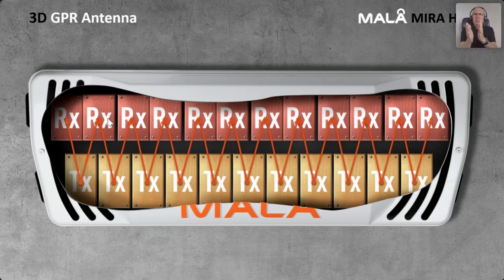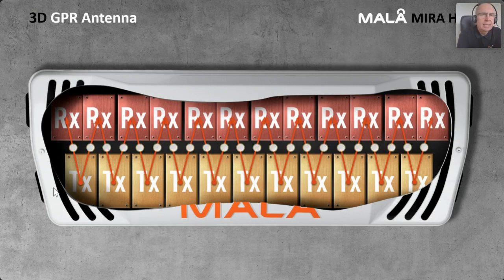So this overlap is actually quite important, because if I put the conventional way of a GPR antenna having a receiving antenna and the TX antenna right behind it, the spacing between the channels is increased. And this overlapping that we're doing here enables us to take tighter measurement points across the array. And this is where we get the very tight channel spacing.